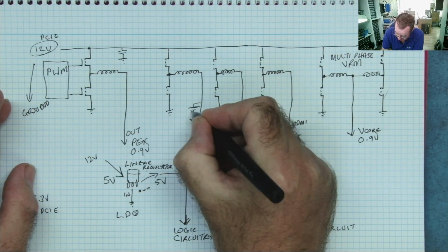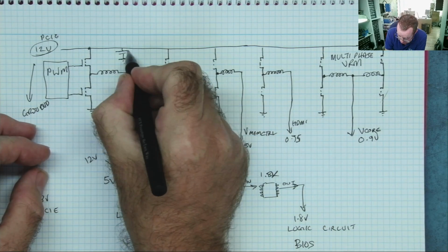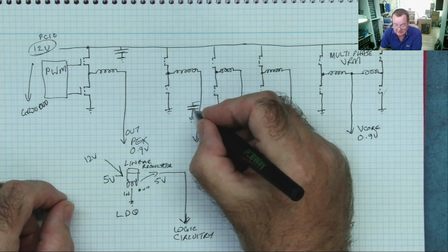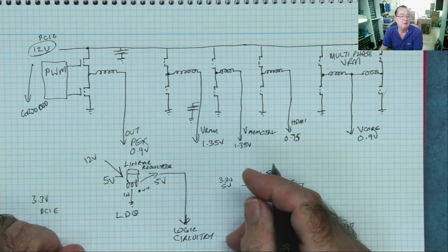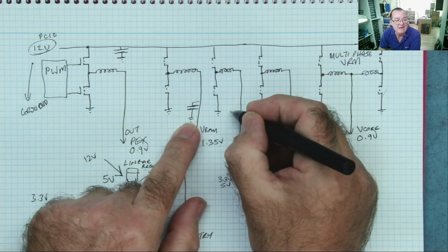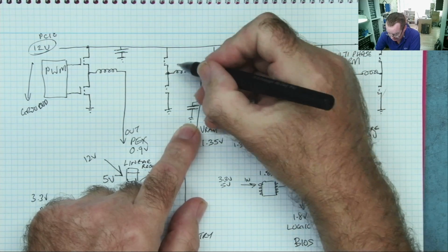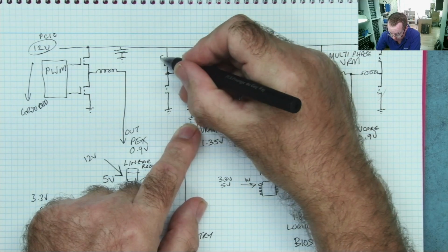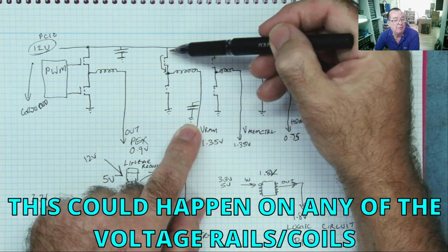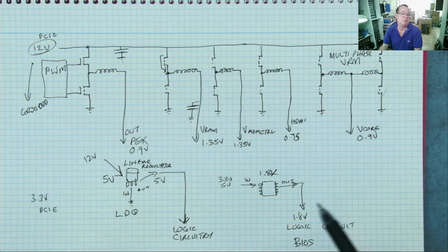This is the capacitor symbol if you're not that familiar with electronics. Okay, so we could have short circuits like that. If these have failed, then we just get a short. But if the short is in the capacitor here that's causing this to read short, then this MOSFET must also be short, because there has to be a path. 12 volts through the shorted MOSFET, through the coil, through the shorted capacitor to ground. Okay?